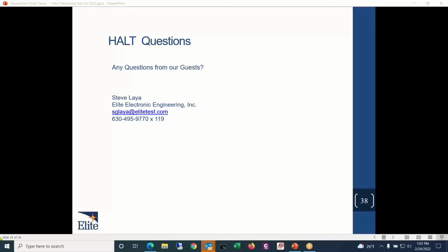And again, this really matters when you're doing a comparative assessment, knowing what that difference is in the placement of products on the table. In a more typical HALT test, where we're trying to test one device and identify its particular product faults, we'll try to get that product right on where we know our hotspot is, just so that we get the most benefit out of the HALT.